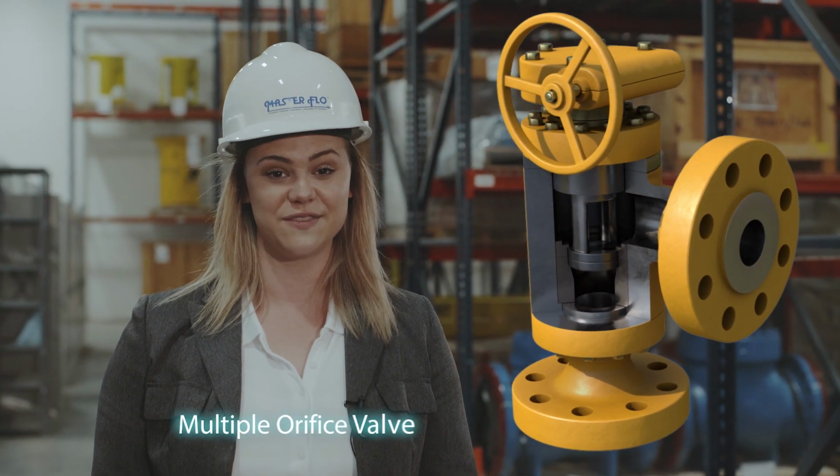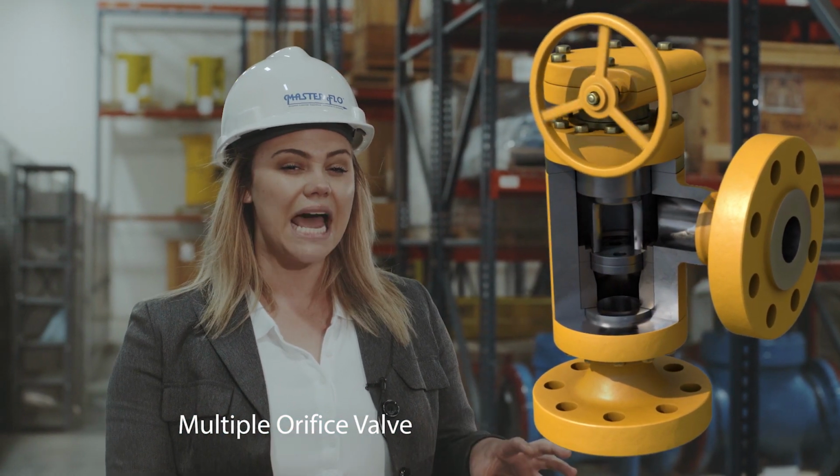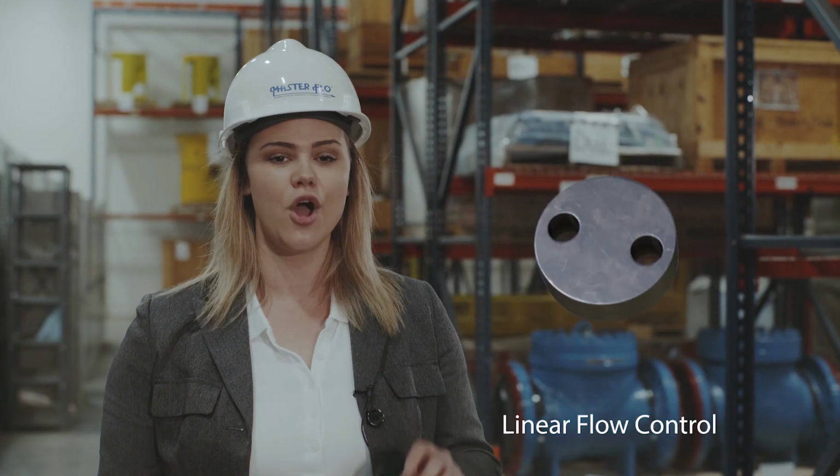The multiple orifice valve design allows for proportional changes in the flow. This type is most applicable when the upstream and the downstream flow are controlled at fixed points. This is not the case in nature. As the well is unloaded, the upstream pressure comes down and the downstream pressure rises. In a refinery application, for example, the upstream pressure is typically fixed.